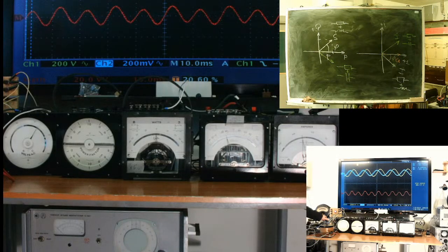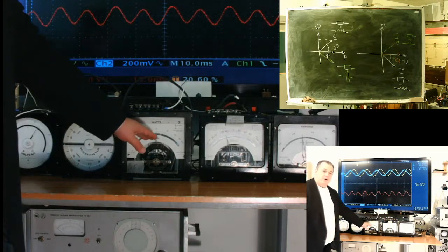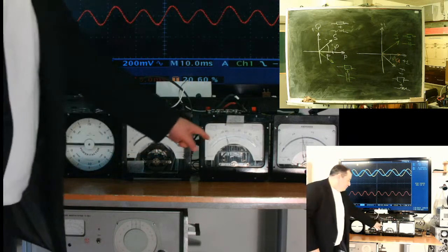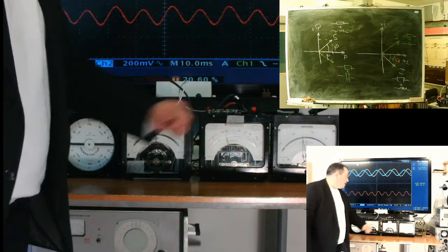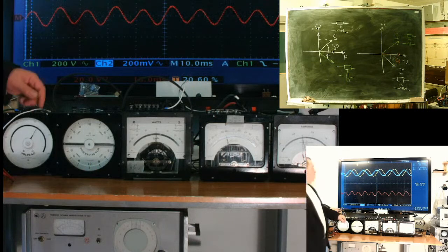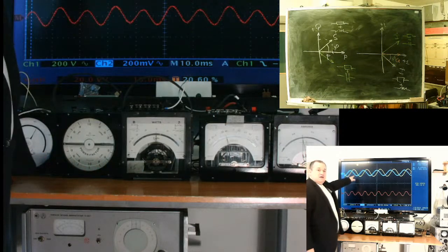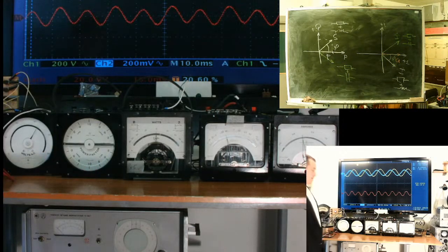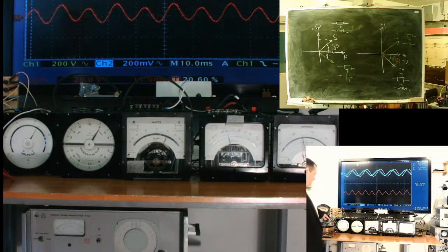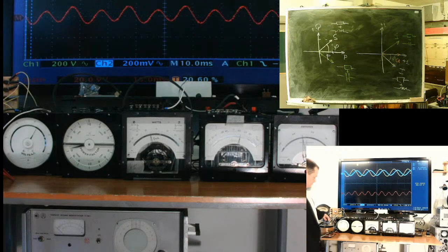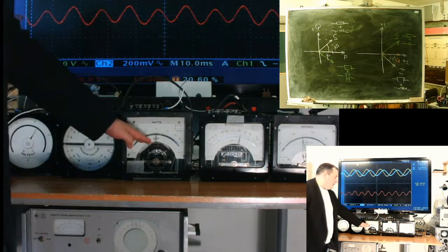Zero active power. You can see current still flows, voltage unchanged, but no active power consumed. We only supply reactive power to the network. Now we see the regime of pure capacitance. In opposite, here it is 0. 0 active power,